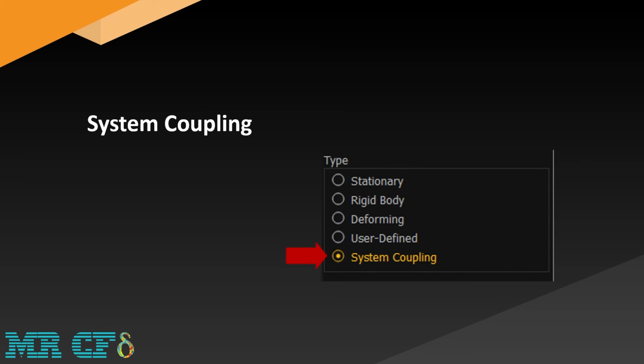For this purpose, in addition to using Fluent software for fluid modeling, transient structural must also be used in the ANSYS Workbench software. Also, in the Workbench environment, the coupling system tool should be used to complete the coupling work between fluid solution and solid solution. Of course, it needs to be mentioned that about the FSI method and its capabilities and applications, we will provide a comprehensive training in full detail in a separate and independent training course.